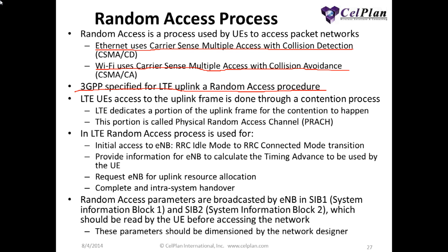One of the reasons for the complexity is that it takes a while. It requires exchange of messages to find out if there was a collision or not. It is a contention process though, and LTE dedicates a portion of the uplink frame for the contention to happen. This portion is called the Physical Random Access Channel, or PRACH.